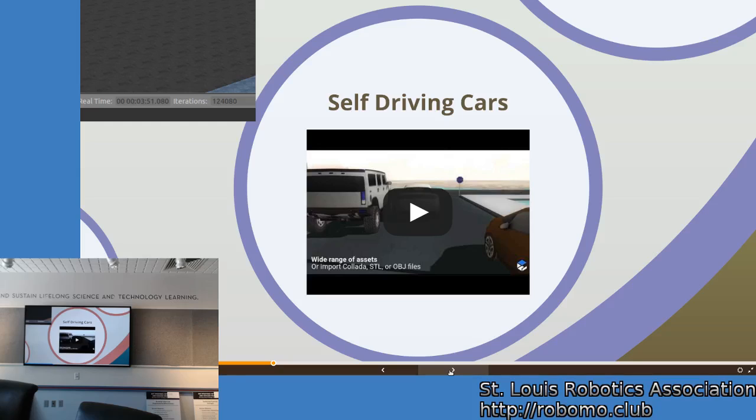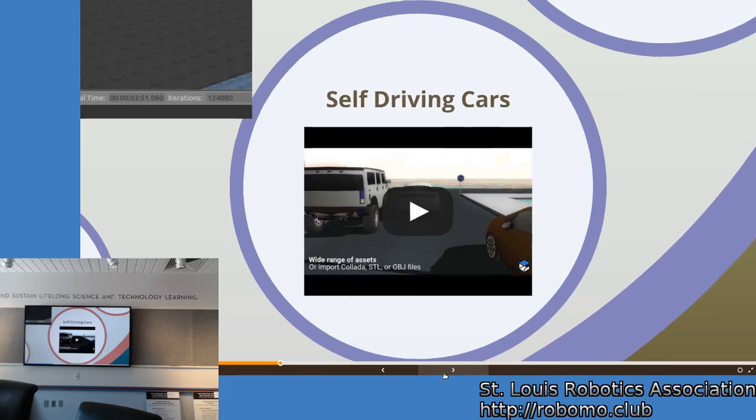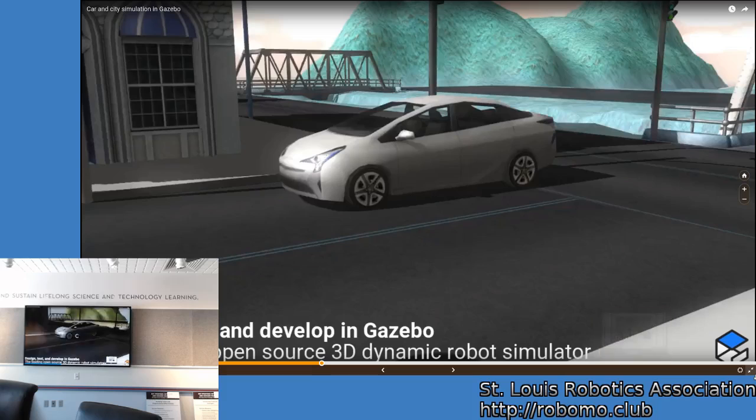No. So yeah, that's the one part I want to try to clarify in this talk, and that is that Gazebo is separate from ROS. Gazebo is for getting feedback from the robot. It's a replacement of your hardware. So you're supposed to be able to drop in this software in place of the hardware, and the software should give you all the feedback that the hardware would normally be getting, and it should receive all the input that the hardware is normally receiving and respond to that in this virtual world. So let me show another real quick. These are only like 1 minute long videos.